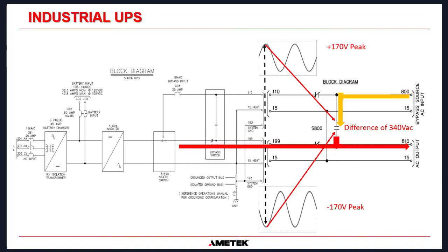It's 170 volt peak. So in truth, if you follow where that contact is, it's going to change. The contact is where it says difference of 340 volts. If you measured across that contact at that exact time with a Fluke, you are going to measure a 340 volt peak to peak voltage difference.